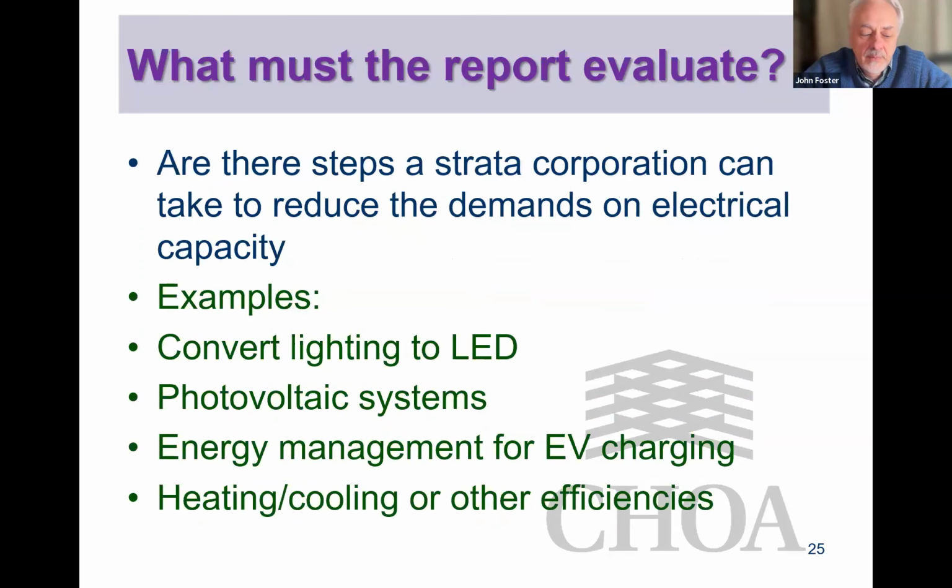And I want to revisit the energy management systems, Tony, as well. That's one of the parts which is least defined. It's not well defined in code and it's not well defined in practice. They are very useful devices and potentially can help stratas save energy and avoid upgrades and replacing transformers or wire. But it's quite another stage beyond the EPR to actually evaluate how they can do that on a given site. So that is an example of something that's generally just mentioned in the reports, but would be a kind of second stage for someone to figure out how to put it in.